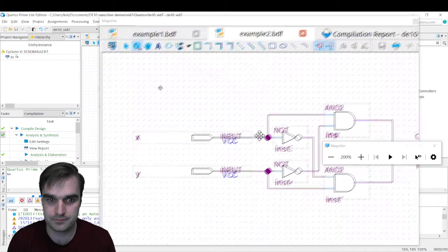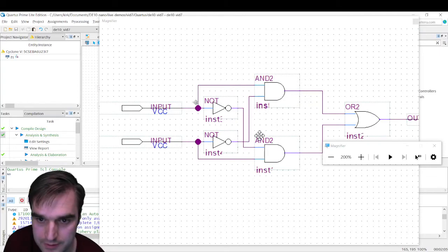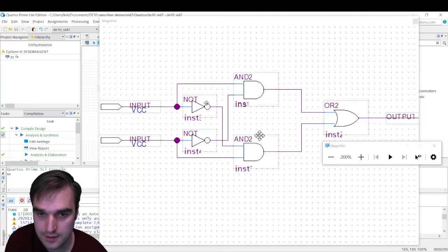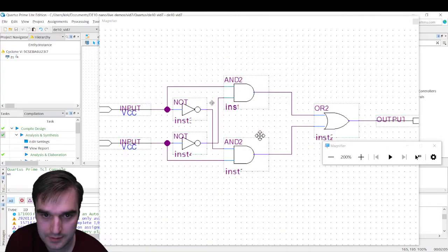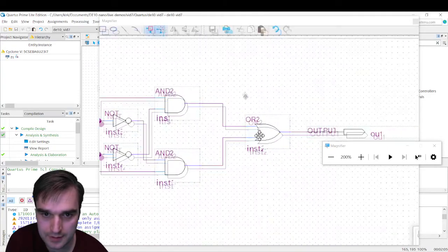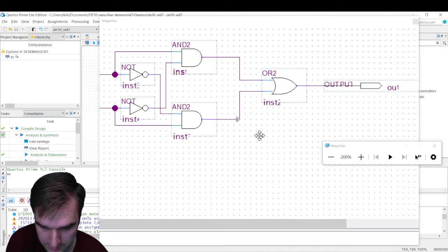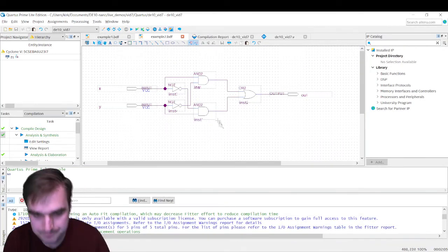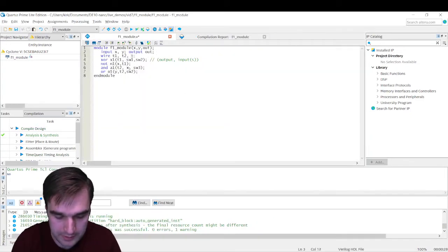And then we're going to need a couple of wires coming out of the NOT gates to hold the NOT value. So 2 wires, maybe 2 more wires for the AND gates. Yeah, so a total of 4 wires. We're going to do this wire coming out of this NOT gate, this wire coming out of this NOT gate, and then this wire and this wire. All right, I don't think it likes me using this magnifier. Let's just ditch that. Cool. So we'll come back over here. We need 2 more wires, so we'll do T3 and T4.